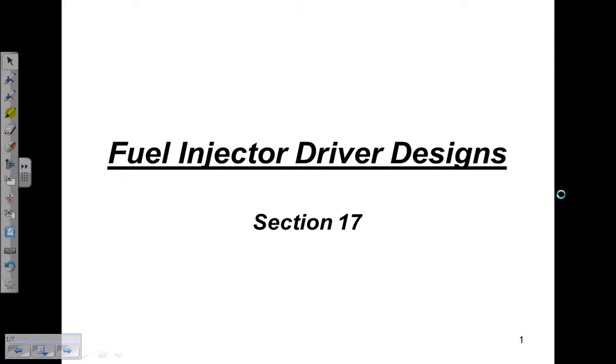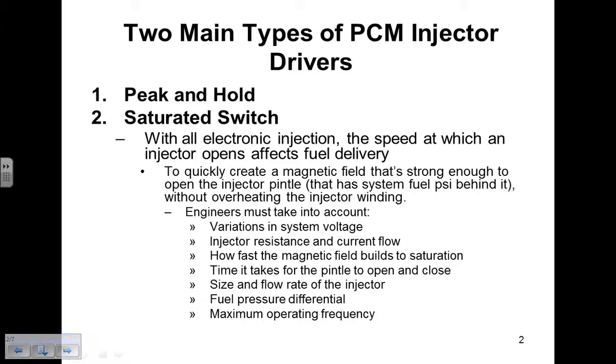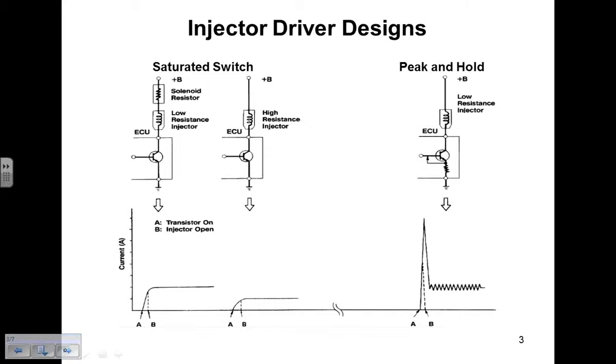Okay, fuel injector driver design, section 17. The purpose of this section is to get you used to looking at the waveforms that you're going to see with fuel injectors, both voltage waveforms and current waveforms. There are two different designs, two main types of computer drivers: peak and hold and saturated switch. And basically, as we go through this, I'll pull up the picture real quick.